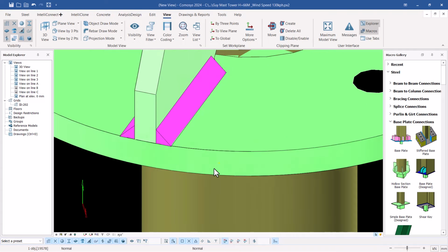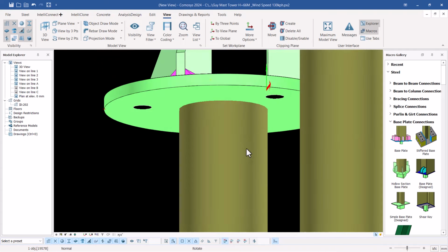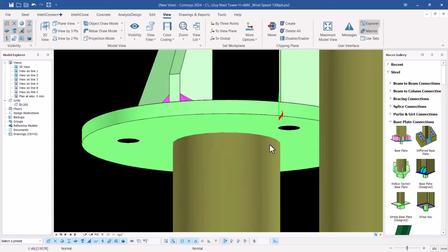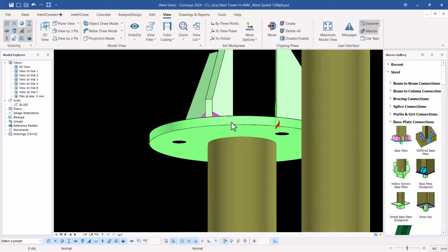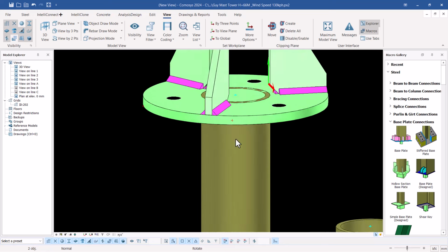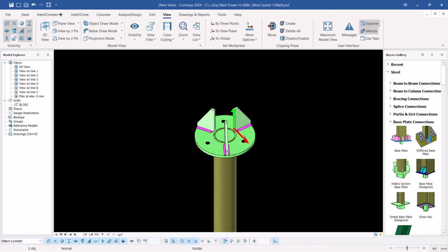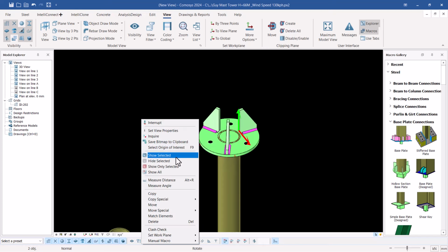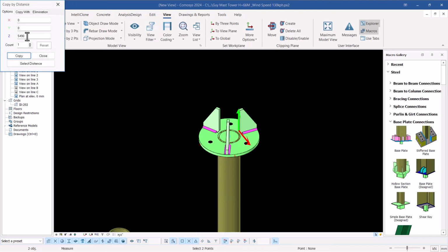So if I zoom close and pick on that and turn around like that, and I want to push it outward so that I'll be able to see them clearly, I'll right click and come to spatial copy. Once I've picked on spatial copy, I'll be able to move them in the z-axis by maybe 300 millimeter. So whichever direction they take, it will still be useful to us.